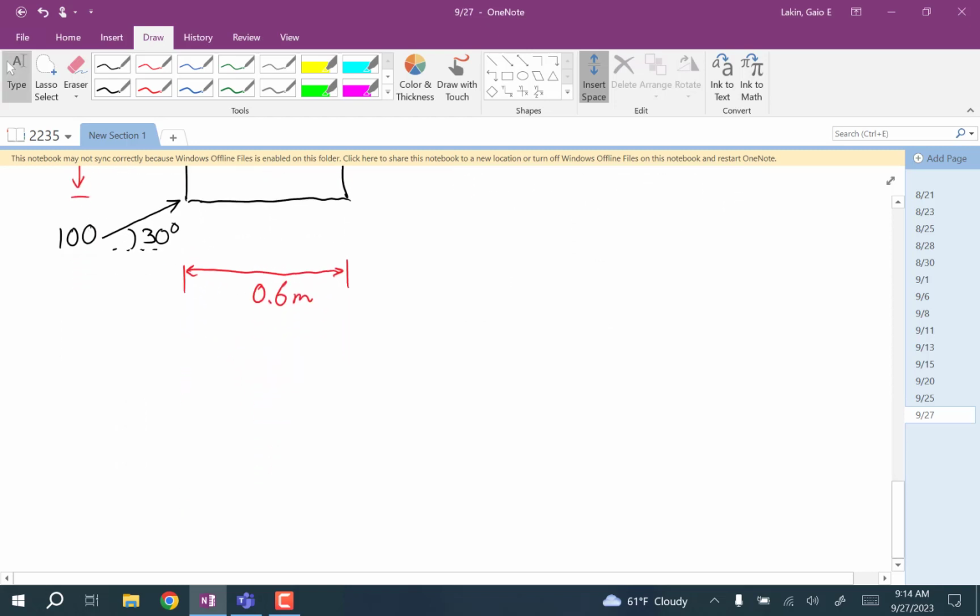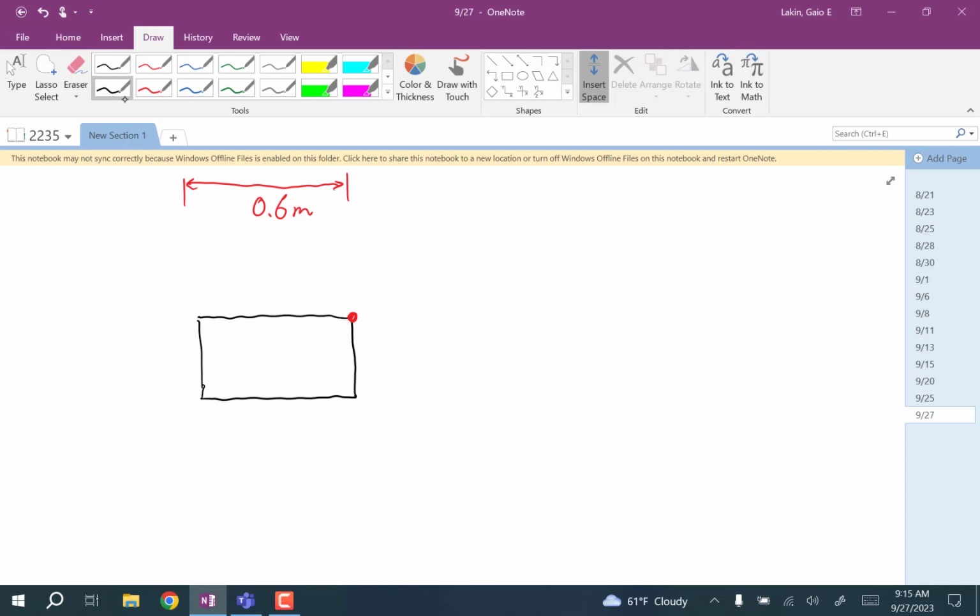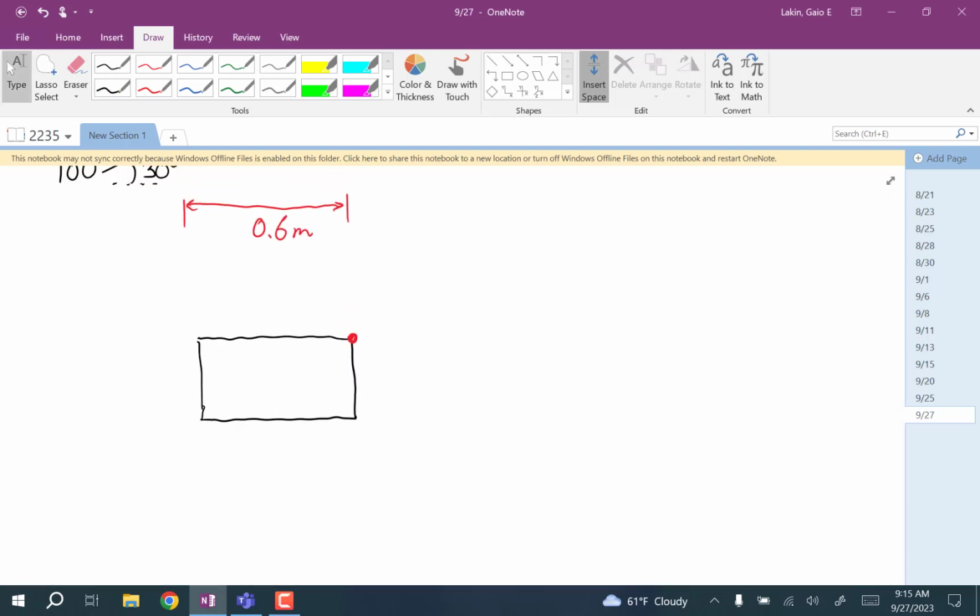And so now if you think about it as components, so there's your about point. Now we're going to think of this as two separate forces. One has a magnitude of 50 like that. And the other one has a magnitude of 86.6, like that. And so the moment is equal to plus or minus, the 86 has a moment arm of 0.3.